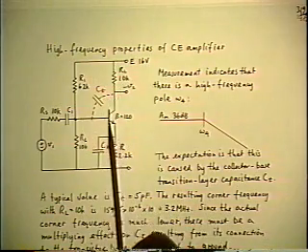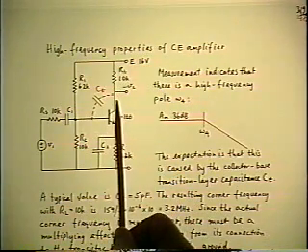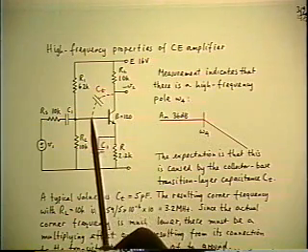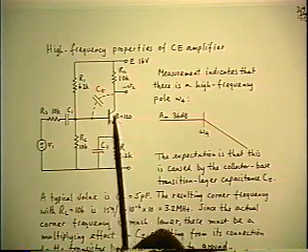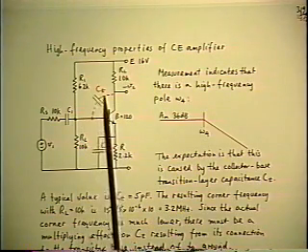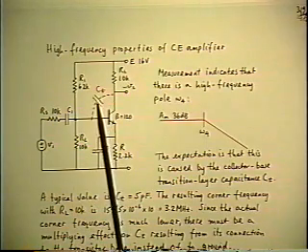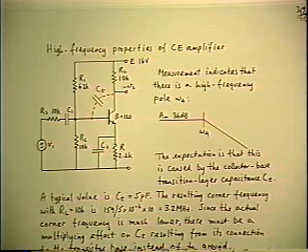The other end goes back to the input of the transistor, which means the current that gets diverted from the output through the CT doesn't go to ground. It goes back into the input and it gets re-amplified. So possibly the effect of the CT is magnified over and above what it would be if it were directly in parallel with the RL.